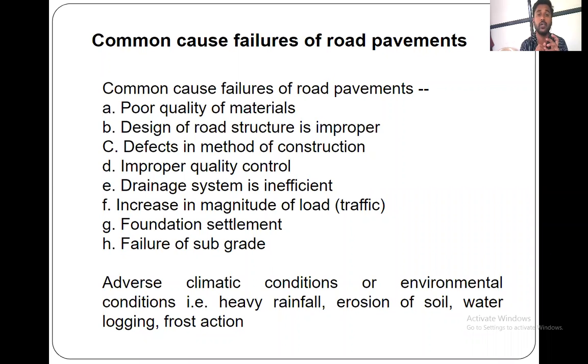Before using the aggregate on the road, we have to follow certain tests on that aggregate, like the crushing test. We have seen the impact test and abrasion value test. Also, we need to check the specific gravity of the aggregate. Likewise, for each and every material, suppose we are using bitumen, we need to understand the specific gravity of the bitumen, softening point, and flash and fire point of the bitumen. All these tests we have to carry out on the bitumen and aggregate.